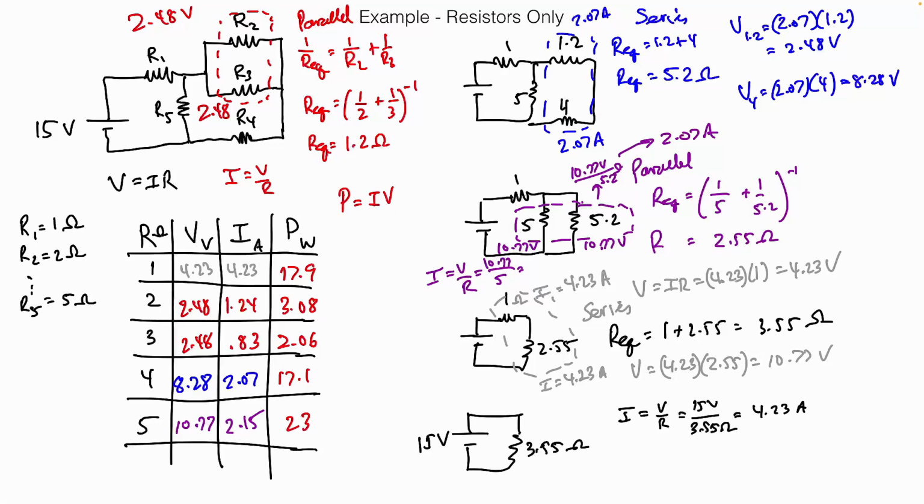Should the currents all add up to 4.23? There are branches here, parallel and series, and things split up and do weird stuff. But energy has to be conserved, right? So where is energy conserved here? What is the one thing we can add up and check? It's the power, because the power dissipated by the circuit has to be the power that the battery's putting out.